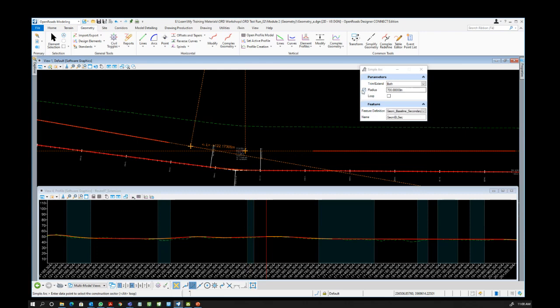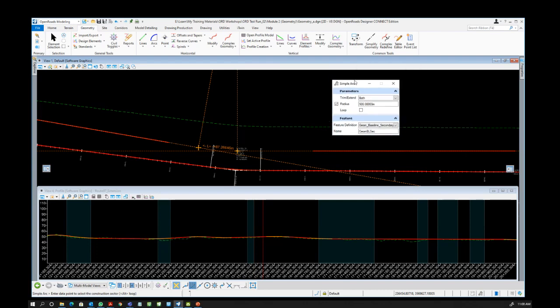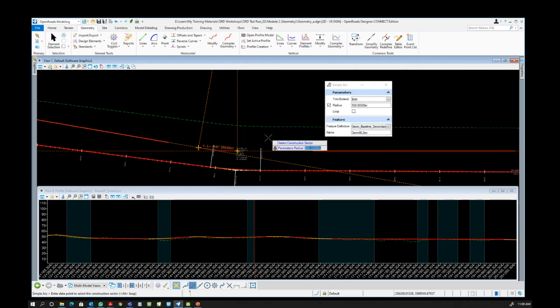Previously, I used 700, that's why it's set to 700. But if you would like to change that, just untick this and then probably change this to 500, which you can do in the tool settings. You can also do that in the prompt, in this dynamic prompt.